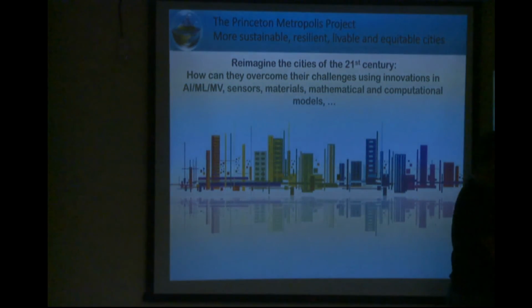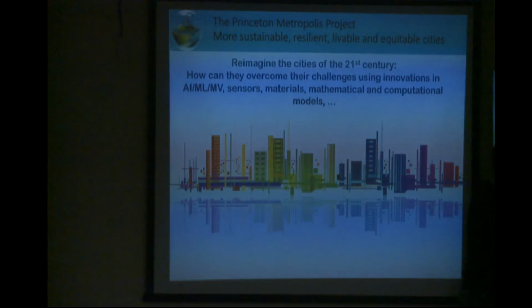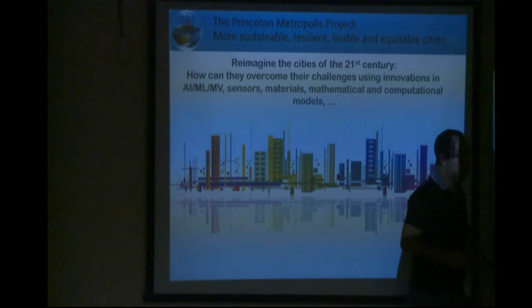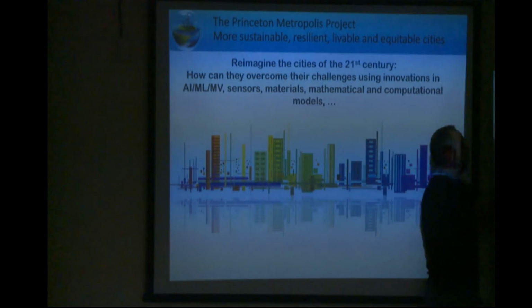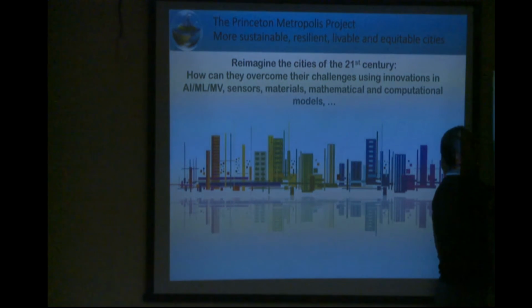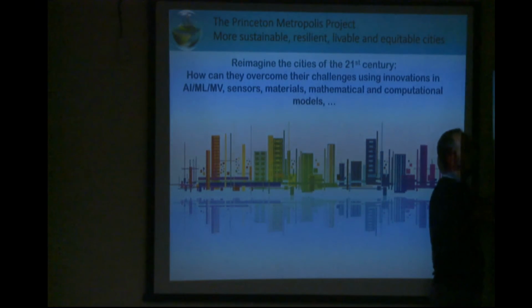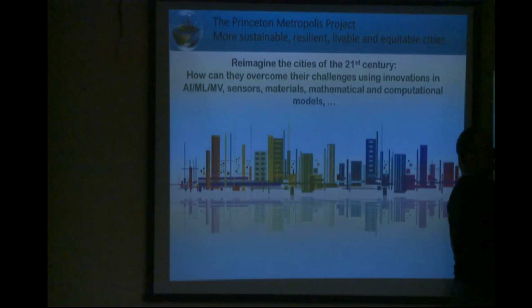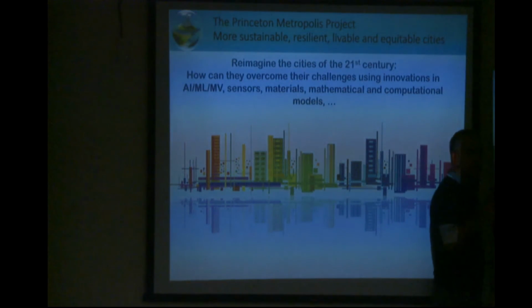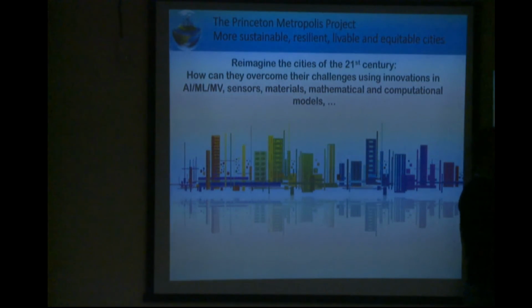In ours, it's different. Imagine this is your building, and let's say that these are your grid cells. If this grid cell is completely occupied by a solid, the velocity should be 0 inside the solid. When you write the equation to integrate the velocity forward in time, it's equal to some right-hand side, which has pressure and everything. The immersed boundary method is a trick whereby you add a force.